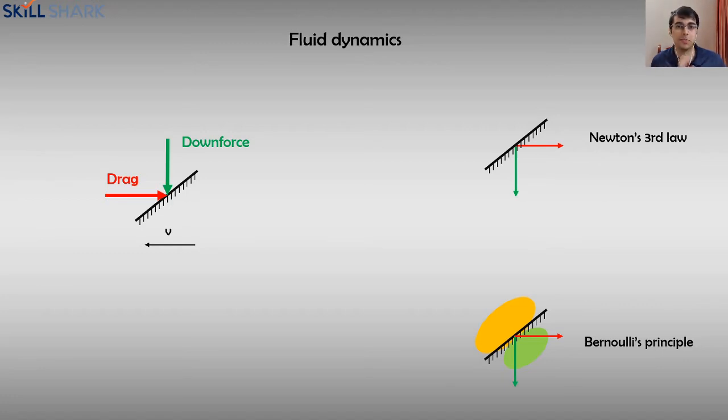And that's what Bernoulli's principle also states. So the sum of the static head, dynamic head, and then the gravitational head at any 2 points of a closed environment in a flow will be equal. So what that means is if there's more kinetic energy on one side of the flow, there's going to be more potential energy on the other side of the flow. Henceforth, in this presentation, when I say that there's high pressure, what I'll be talking about is high static pressure.